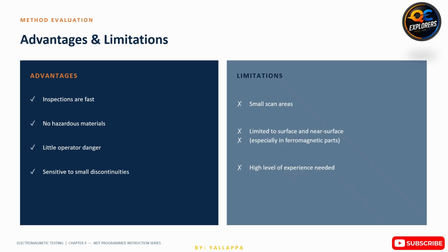Perhaps the greatest technical advantage is its excellent sensitivity to small surface and near-surface discontinuities. Tiny fatigue cracks that may be difficult to detect visually can often be identified at an early stage using properly calibrated eddy current equipment. However, the method also has limitations.